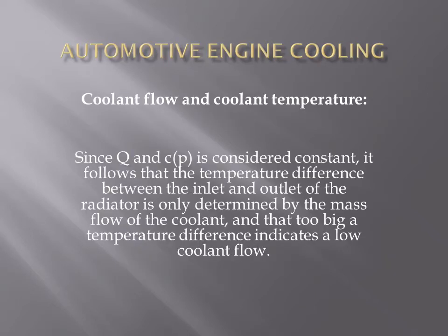Coolant flow and coolant temperature, we just put it in words again. Since Q and Cp is considered constant, it follows that the temperature difference between the inlet and the outlet of the radiator is only determined by the mass flow of the coolant, and that too big a temperature difference indicates a low coolant flow.